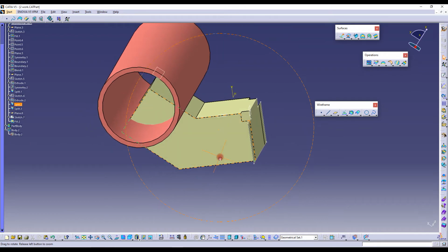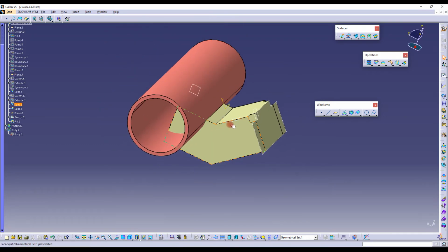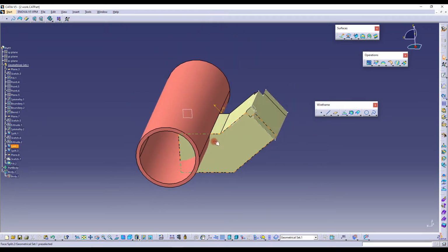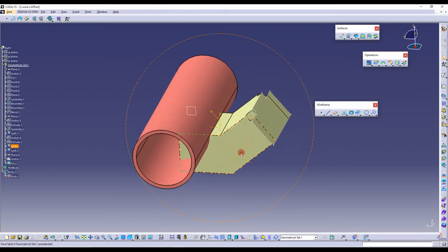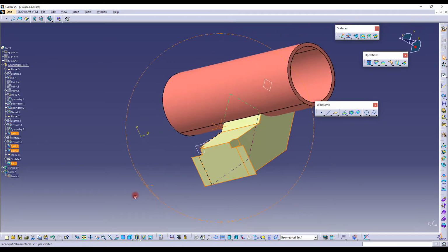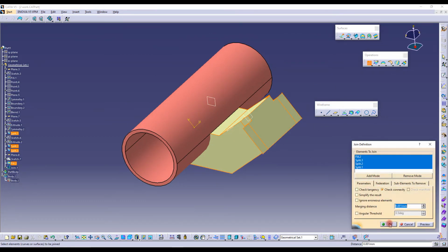Now all we need to do is join all of these surfaces, give the edge fillets, and create a symmetrical portion on the other side. So now we will have to join all of these surfaces. For that, we need to select all of the shown surfaces. So this fill which we recently made, this split 1, 2, and 3. So this constitutes all of the surfaces, and select join and press OK.